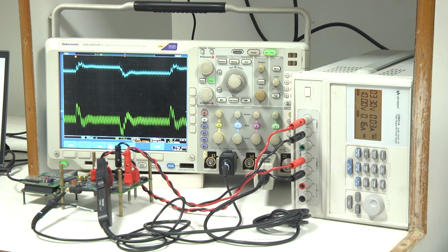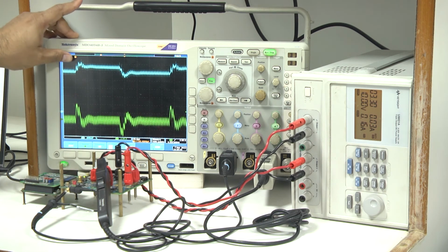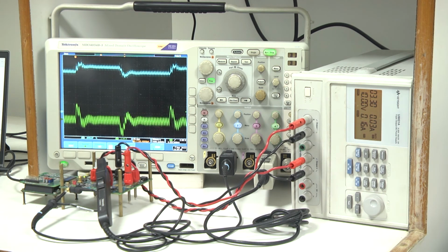So, this is the response of current mode control, and since the reference is generated from inside, there is no such delay, so it responds almost immediately. Because of the finite output impedance, we cannot make the closed loop faster than 1/5 or 1/6 of the switching frequency, called the closed loop bandwidth, because we also discussed the small signal validity. So, this is what we have about the mixed signal current mode control.